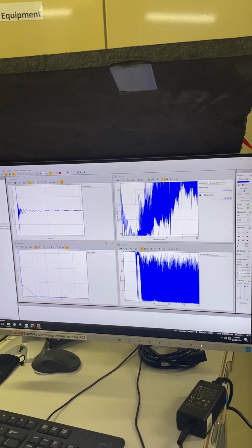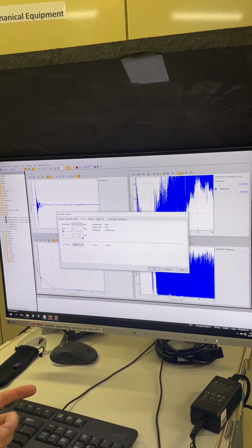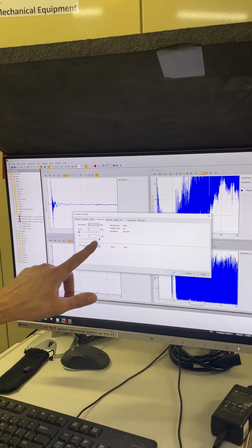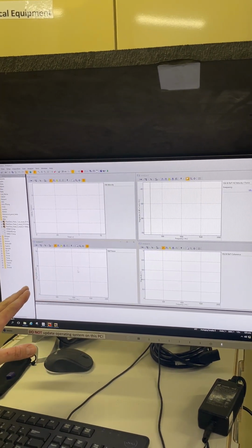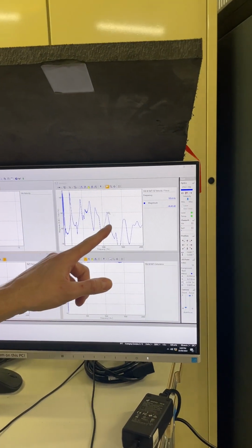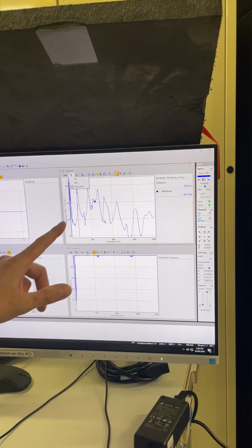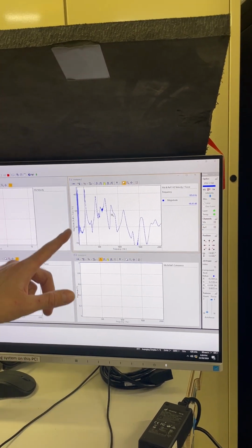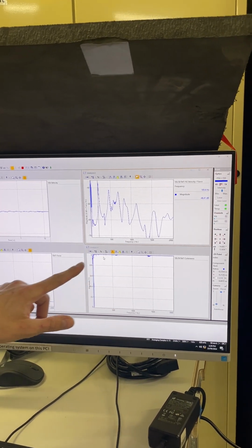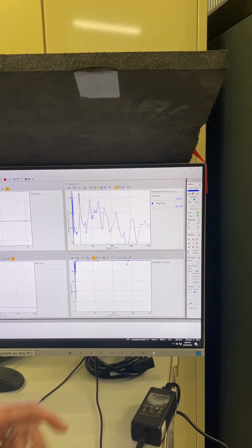Let's have a look now if I reset the A to D parameters back to around about a couple of kilohertz and adjust the spectral lines accordingly. So back to 1.6 seconds of excitation, 3,200 lines. What we really are interested in is to get good FRFs. So up here I've got an FRF, I'm showing vibration and reference. This is the response measurement divided by the impulse excitation, the force transducer measurement, and very nice coherence function here as well. We're looking for coherence to be 1 across the entire frequency range.